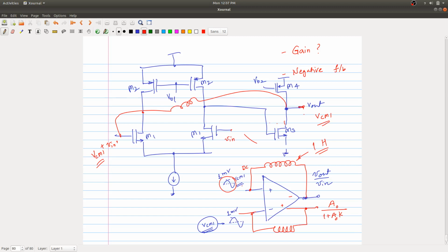So when you are doing this, whatever the DC potential was available here, it will go here. And when you are going at high frequency, this is an open circuit and it will give the gain. At low frequency, this is exactly VCMI or DC potential, whatever you wanted, it's there. So this is what you generally have to do for simulating the op-amp gain, phase, right? So what we have done was a little bit incomplete, but without understanding this approach of common mode, we cannot go further. Unfortunately, this is not given in any book.